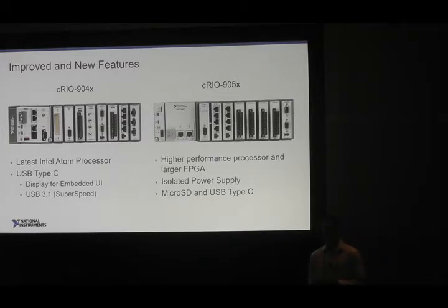We want to make sure to keep that around, but instead of having a dedicated port just for that, we now have in this top board that you see here something called dual role support, which allows it to act as either a USB device or a USB host. So you can either connect to a laptop from it and develop, deploy and debug your application, or you can use it as a host and connect up to some device if you want. The bottom port, just below that, has host capability, so you can use it to connect to other devices.